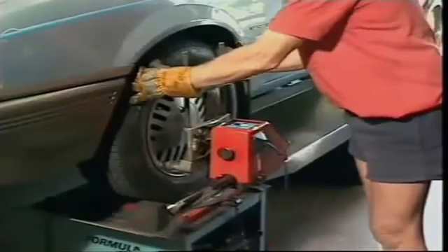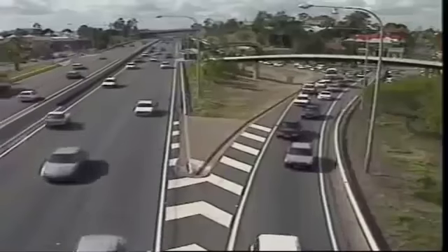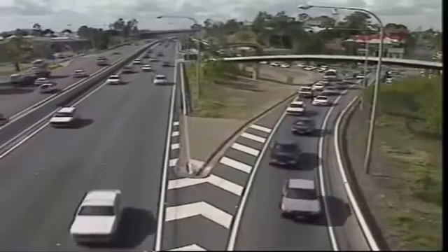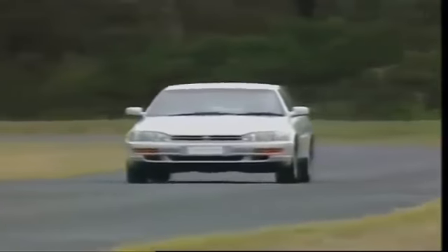The amount of camber is now reduced, so that most cars have what is called zero average camber to give long tire life. This is because when a vehicle is in motion, zero camber is difficult to maintain. Changes in running camber can be caused by road irregularities and load variations.